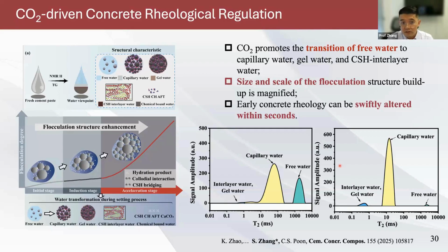Different particles interact and bond together through physical and chemical interactions, and form a large structure. Even though it's flowable, we call it a floc, and that is closely related to the water status. And CO2 can help to significantly enhance the size, scale, and strength of the flocculation at early age of the concrete.